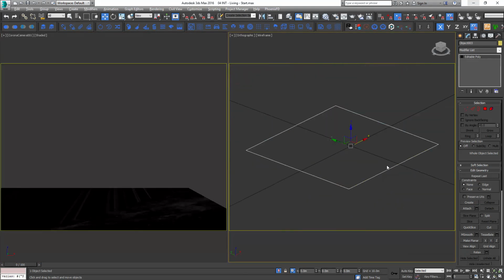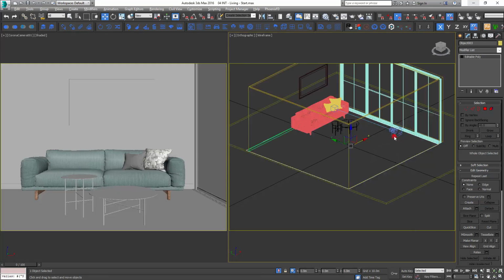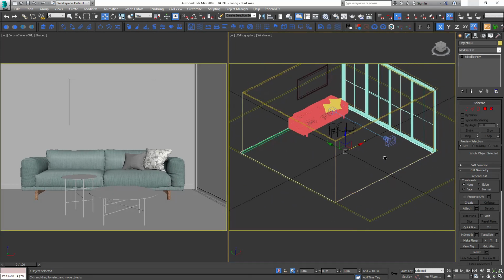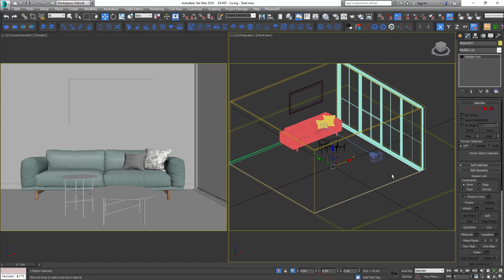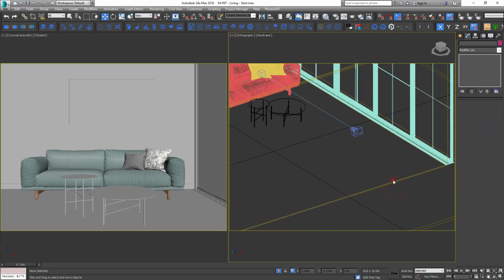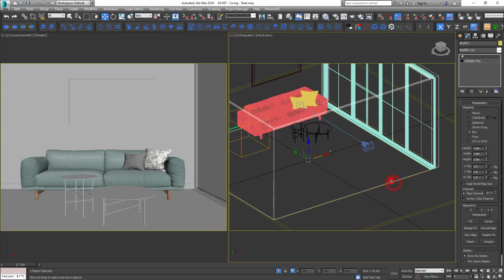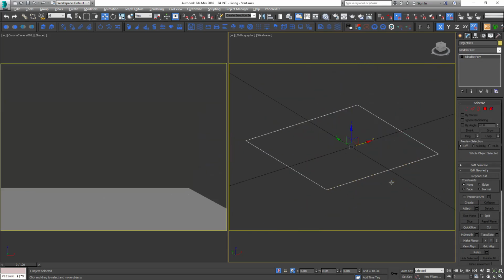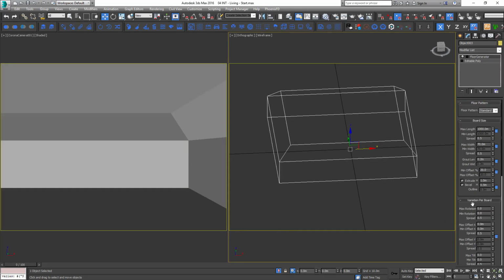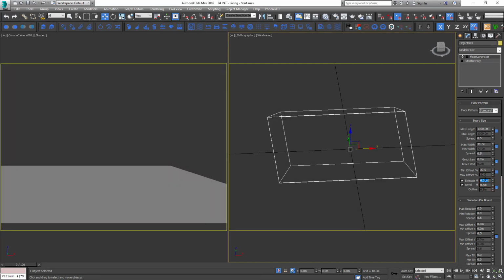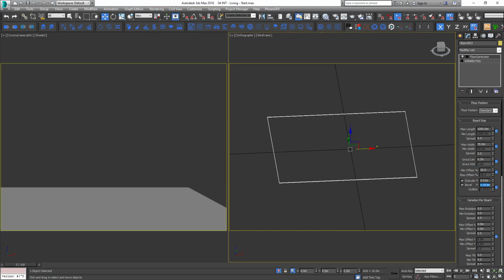Let's select the base and use the floor generator script to create nice floorboards. We need to use proper values in here. So let's say 1 cm for the thickness of the boards and maybe 2 mm for bevel. We can set the 1 mm grout and the size of the floorboards 1.5 meter by 10 centimeters. You can set your own values. Do it as you feel it.